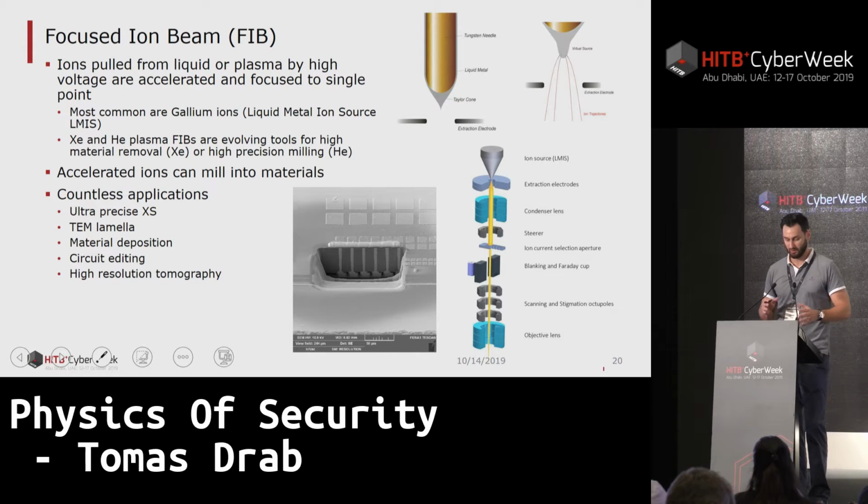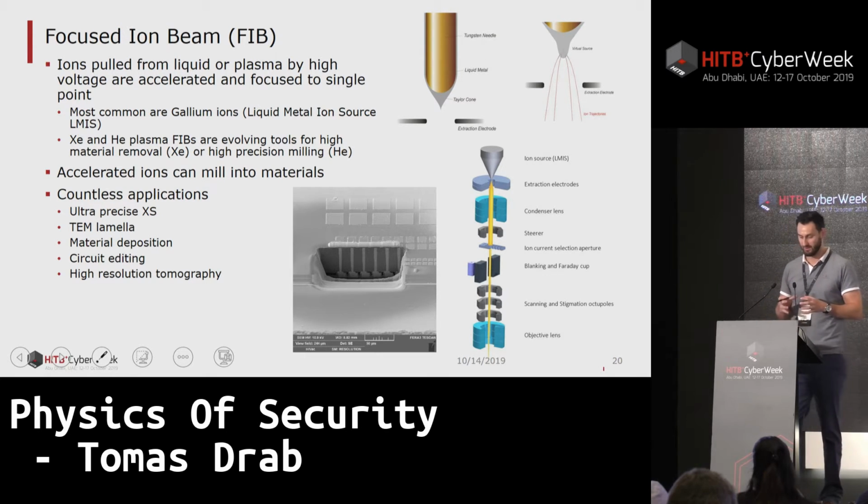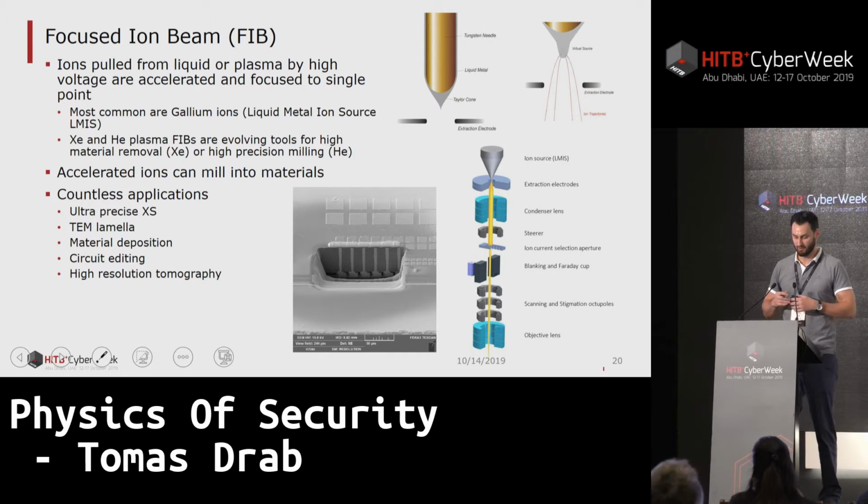If you want to do some adjustment in the chip, focus ion beam is the tool you have to go to. It's basically like the SEM, the scanning electron microscope, just instead of electrons, you're shooting ions, which are much heavier, and you can remove the material using these really fast accelerated ions. But not only that, you can also deposit material.